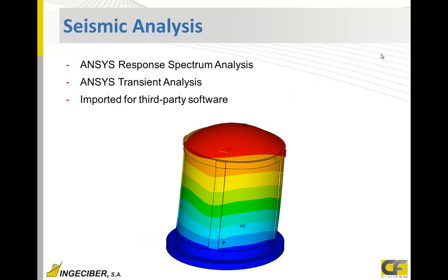For the seismic analysis, you can perform it in whichever way you like, for example with ANSYS response spectrum analysis. CivilFEM works on the ANSYS result files, RST files, reading those results, for example stresses, and integrating those stresses to create the equivalent forces and moments in the dummy cells, and checking. So it doesn't matter how you perform your seismic analysis.